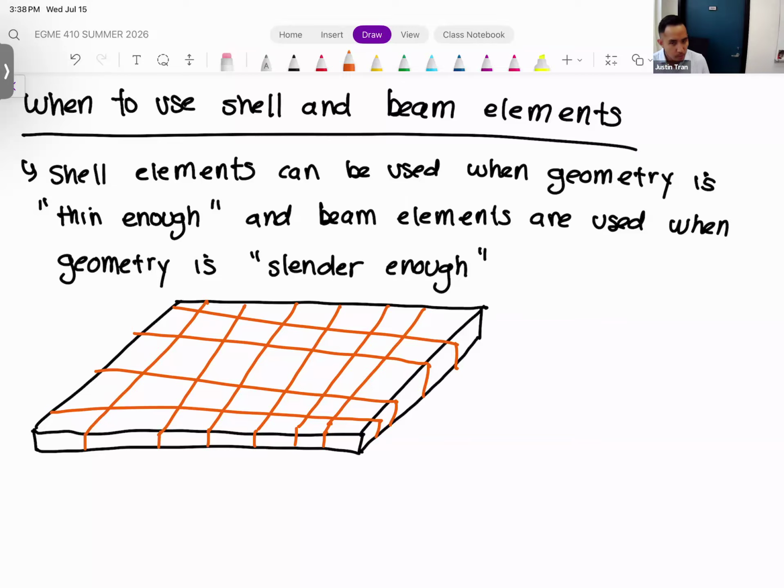And so one thing you can do is make your mesh smaller to accommodate this. In other words, we can refine the mesh enough to add elements just like that. But remember, we control mesh size by only a single edge length. And remember also that generally speaking, ANSYS is going to want to maintain high quality elements.